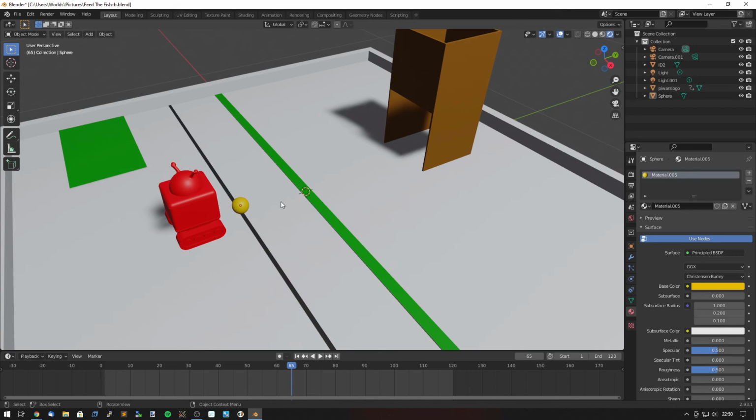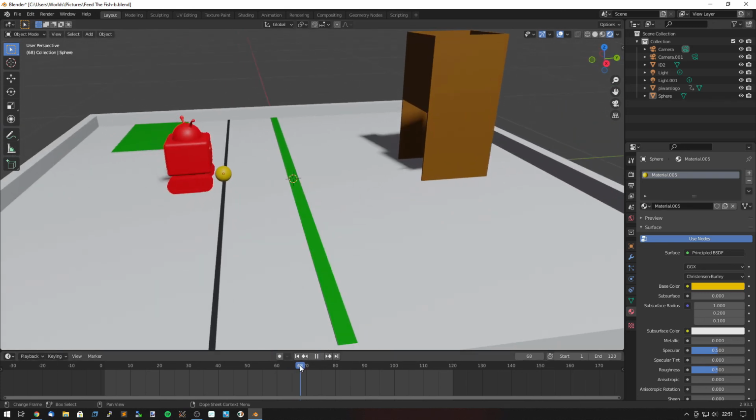Now you could mess around with the physics and get this to be some sort of rigid object and have the robot also as a rigid object and smash into it and roll it that way. You could go that way, but for this kind of animation, it's so simple. I pretty much just want to be moving this robot to the position on the keyframes down here, the frames. I can say, where is it about to hit it? There. That's where it's about to hit it. So you can see if I select the robot, this shows me where those keyframes are. If I select the ball, it has its own set of keyframes. So I now need to select the ball, hit the I key and say location and rotation. So I've made a keyframe of where the ball is right at the beginning.